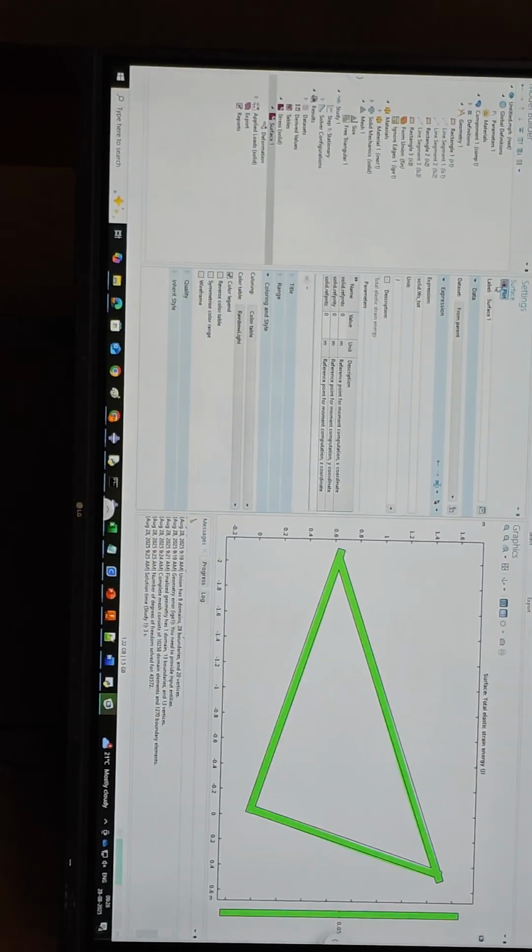So we go to this little icon here. Click surface first, then go to this little green and red icon, drop down on it, go to solid mechanics. Now, in solid mechanics, you notice there's a continuation between what we added as a physics and here. Then go to global, we want the overall strain energy. So we go to total elastic strain energy. We double click it, it enters the expression here with its unit, and all you've got to do is plot.